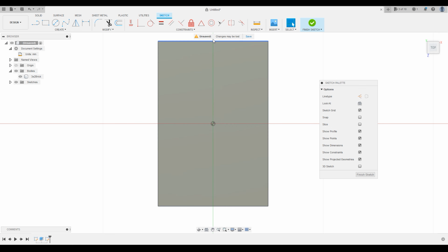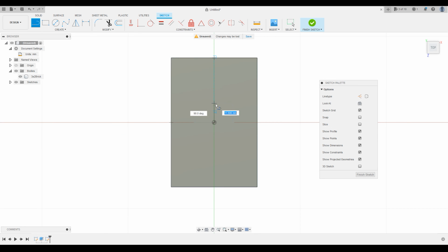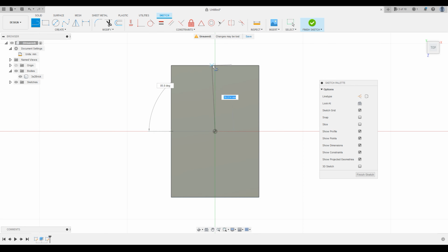The first thing I'm going to do is draw a horizontal and vertical mirror line or center line. So I'm going to go up here to select my line tool, hover over to the origin, and you can see it brings up the blue square. That means it's going to snap. As I drag up, it's going to snap to the midpoint of this edge. Then I'm going to click on the center again and out here to this edge and hit escape to exit that tool.